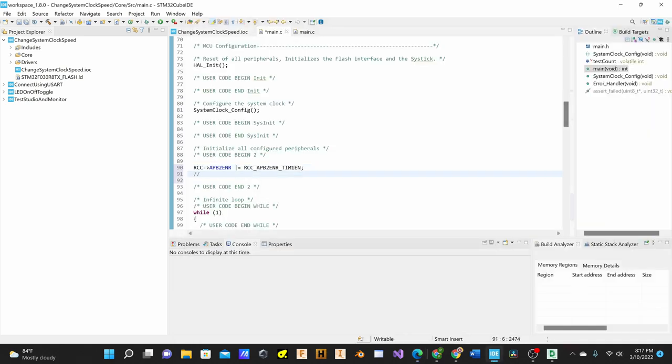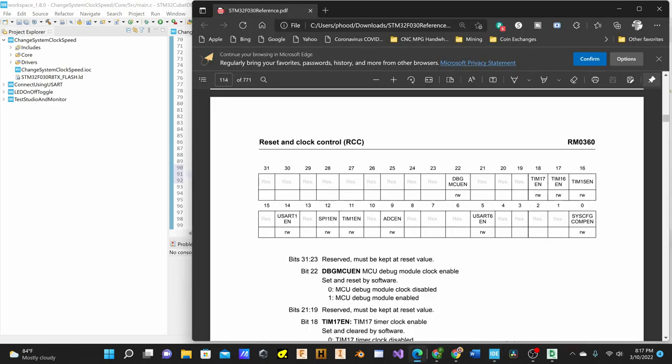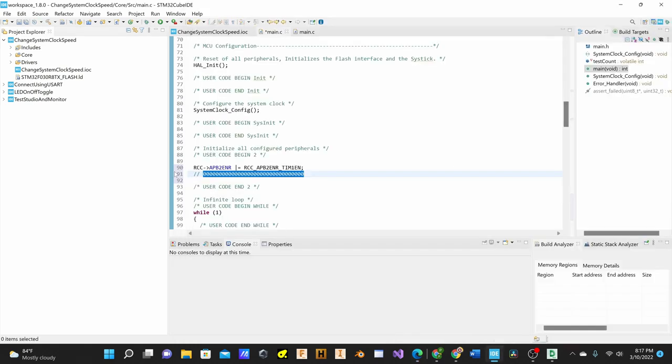I'm going to use a comment for this. This is a 32-bit number, so this is essentially what the register looks like, because you can see it has 32 places from 0 to 31. And what this is showing you here, taking a number 1 and shifting it 11 spaces, is doing this: putting a 1 in this location. That's all it's doing, and it is as simple as that. So this value here is the same as this value right here, which is the same as this value here, which is using the bitwise shift operator.